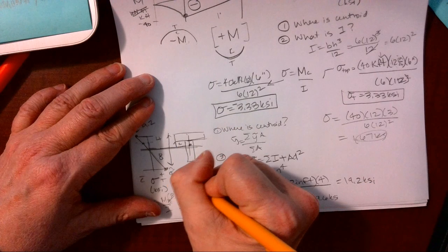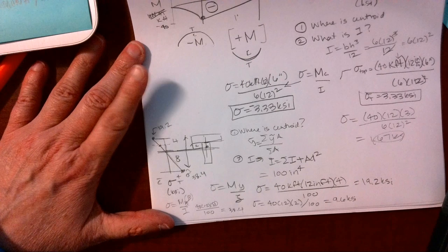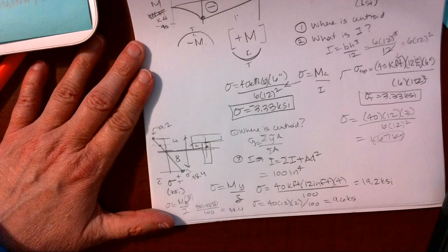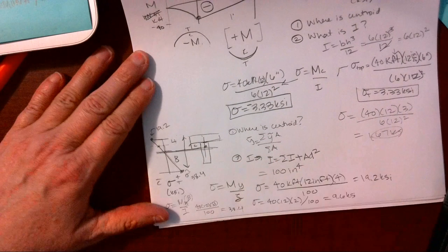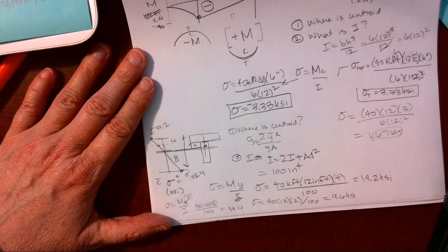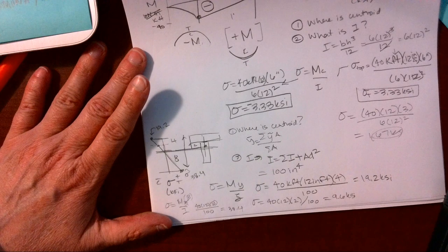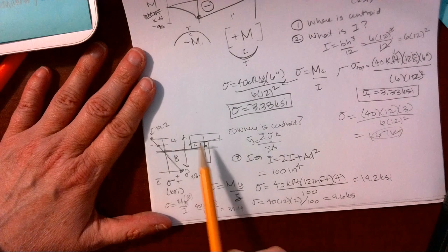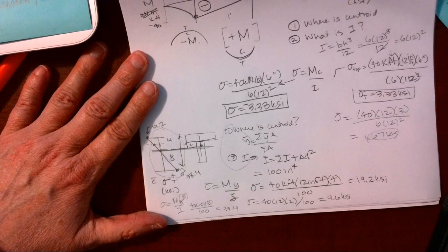Okay, so unlike stress of P over A, where it's the same throughout, and unlike our shear due to twisting, torsion, where it's just linear from 0, something more like that, when we start looking at stress in a beam, we can have very different numbers when we're looking at stress at the top and stress at the bottom, which is why it's imperative that if you have a max positive moment and a max negative moment and you don't have a box or a rectangle, you actually have to check both my positive moment top and bottom and my negative moment top and bottom,